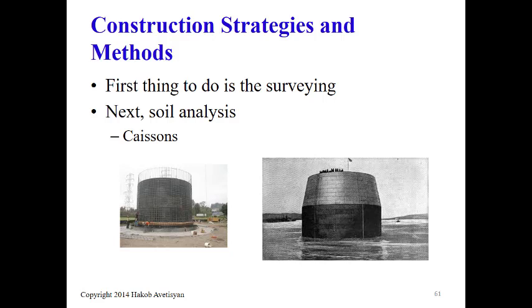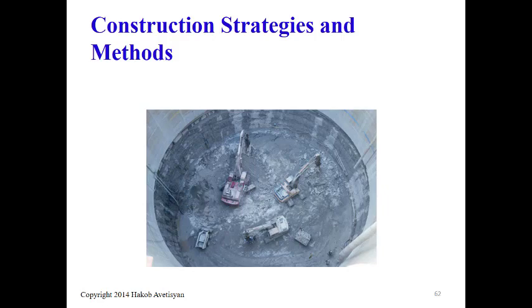These are typically used for building foundations and support for bridges, and the system is pretty interesting and really exciting. Another picture shows how big a caisson can be. You see this setting that has the bottom part as the soil, where the construction equipment operates and excavates the soil, and the caisson penetrates into the media under its own weight.